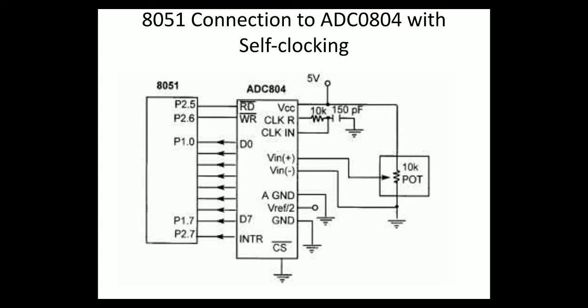Also, the need of a clock for analog to digital conversion is a major question: why do we need a clock for conversion? The answer is that whenever we sample an analog signal and convert it to a digital signal, we need proper time stamping. That is how the sampling rate needs to be kept constant. The variation is not acceptable.